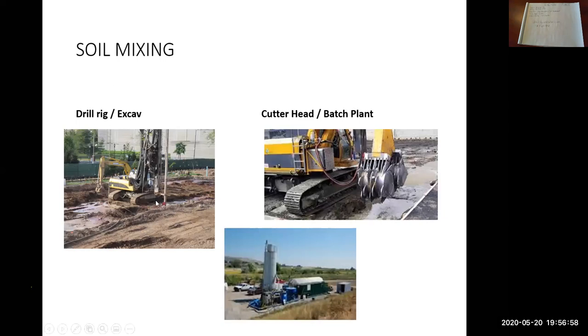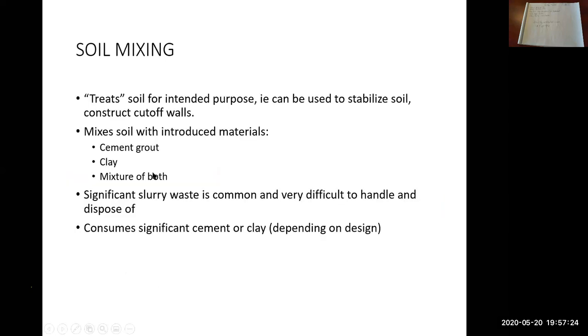So for soil mixing, we have a drill rig to get down to the depths that you need to get to, and special attachments for mixing the materials, batching up the materials. Again, there are specialized companies that do this as well. Again, it increases the density of the ground, or it can, if you're using a cement mixture, that will increase the density.